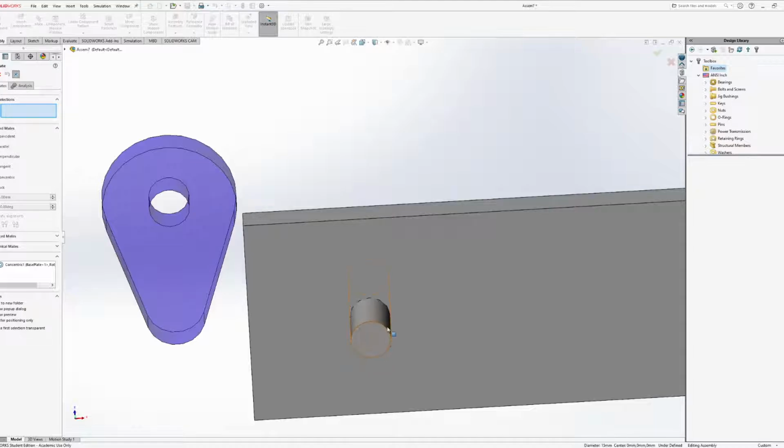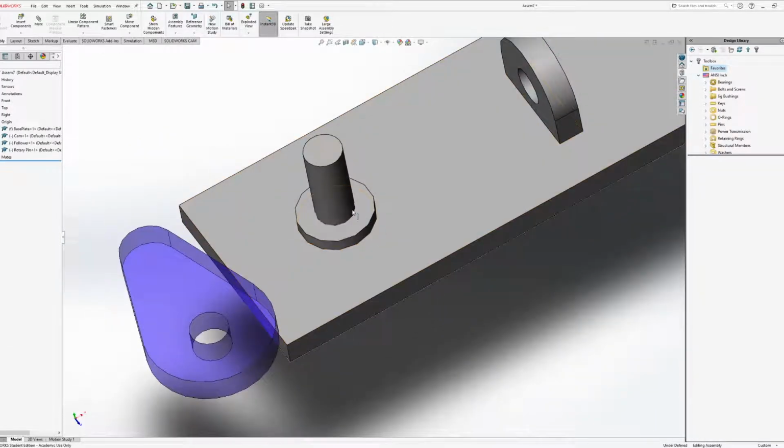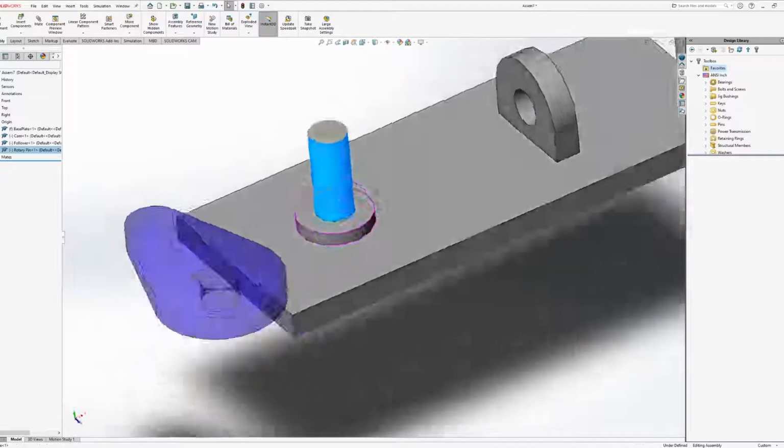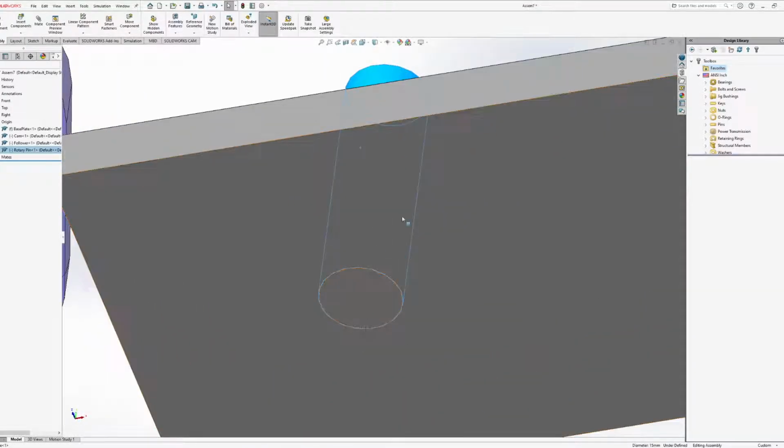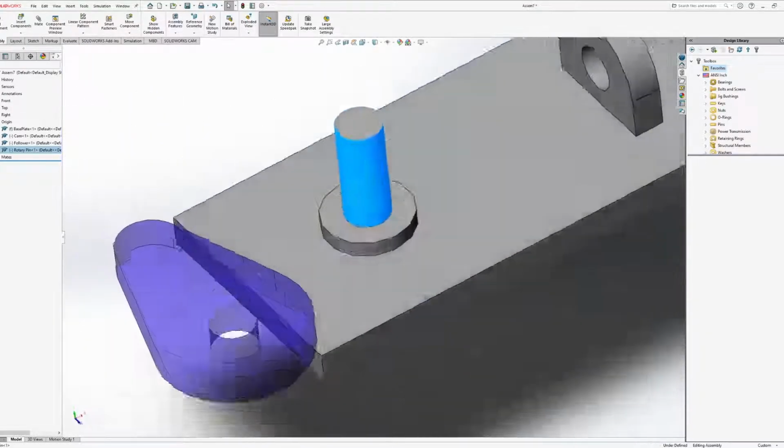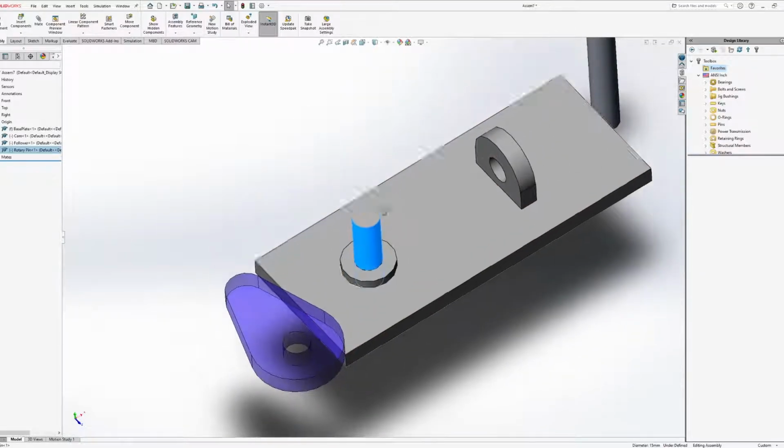And actually, I'm just going to show you why I'm doing that instead. So I will do the edges first. If I do those edges first, then, okay, so this does actually rotate. Sometimes you want to play around with these things here because if I had done perhaps maybe a coincident, it might not have moved as properly as it should. So this is fine. Those mates are fine.